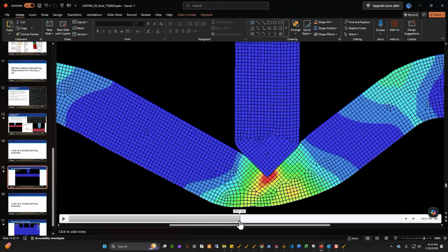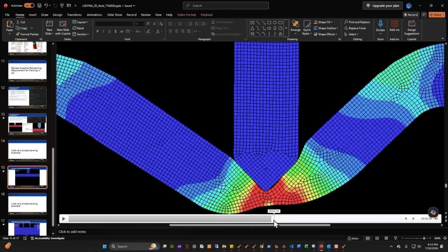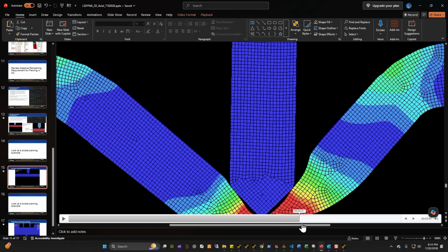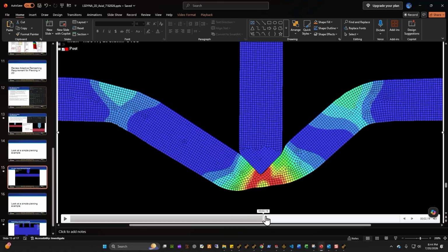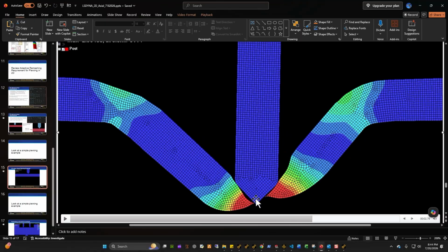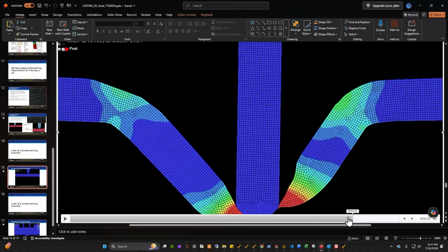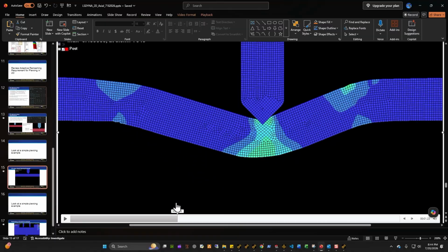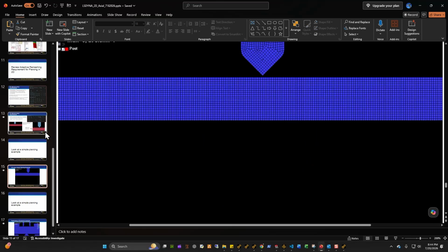Instead of stretching the element as you cut into it, you just remesh that interface to generate more elements until you fully detach the two parts. And that is where you have the intended behavior for separating a single body into two different bodies through nothing but remeshing along the cut interface. Okay, and that's the first example I'm going to demonstrate.